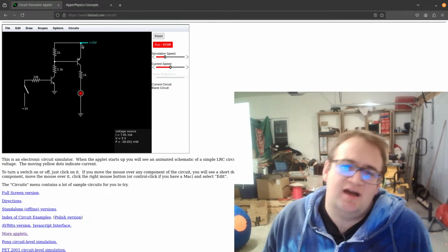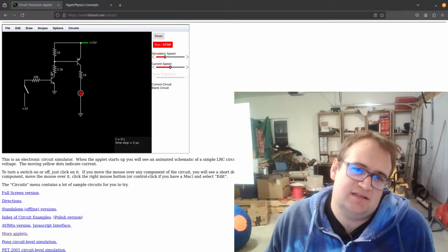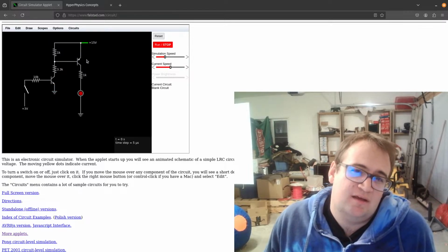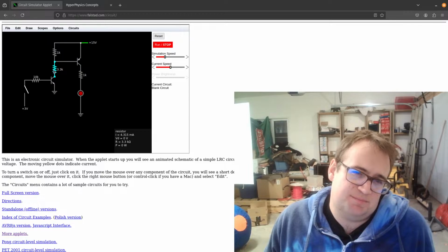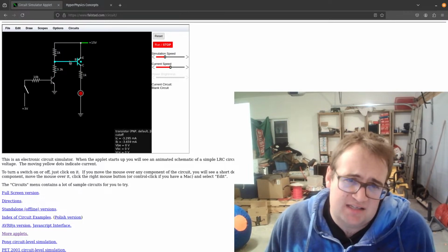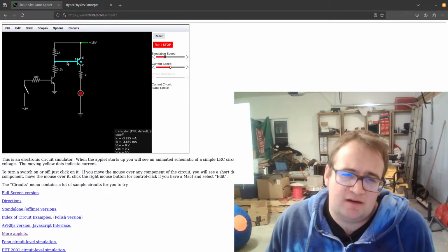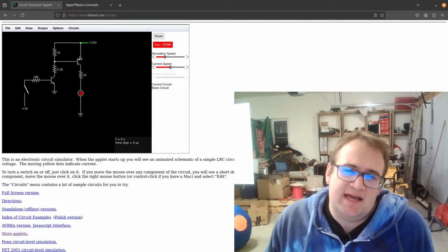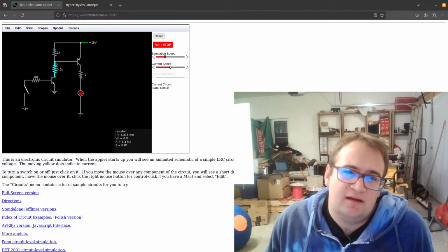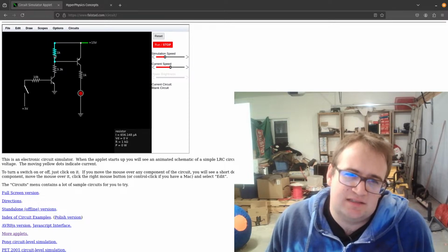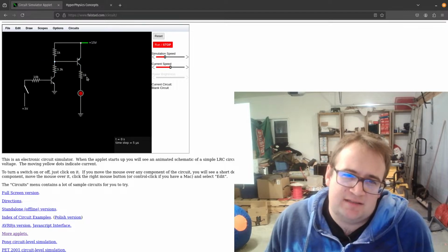And then I see what will happen. Since this will be calling for extra, then it will activate this PNP transistor as well, because some current will flow through its base to try and satisfy this, which then will require the rest. So since only 1K is here, that means the rest of this 3.3K is there, and that means that this will be burning up.